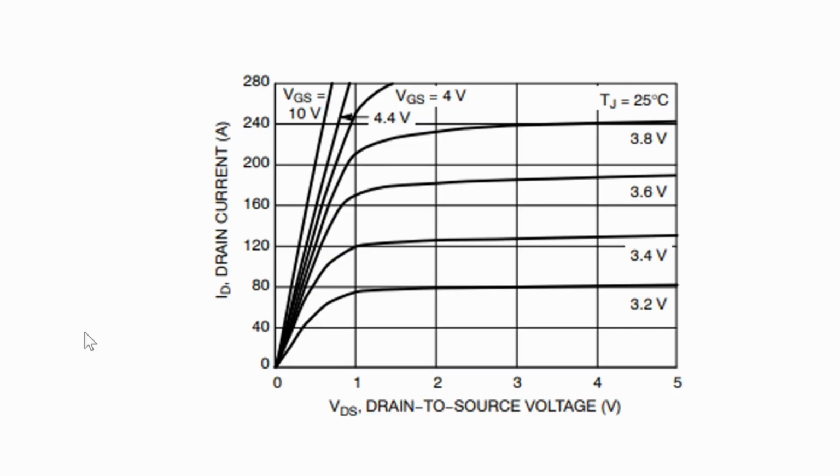This might look confusing at first, but carefully look at this graph. This is just an example graph of a nondescript real-world MOSFET. Now the most important thing is seeing that for any value of VGS, so the gate to source voltage that's noted by each of these different lines, there is a different maximum current that can be reached. Now this might seem confusing at first. I often struggle interpreting graphs, but if we now look back at our previous circuit, we can prove it.